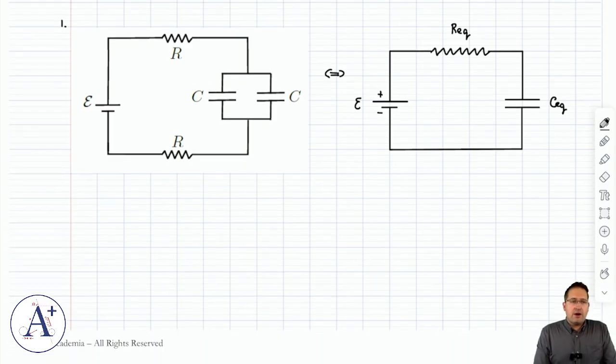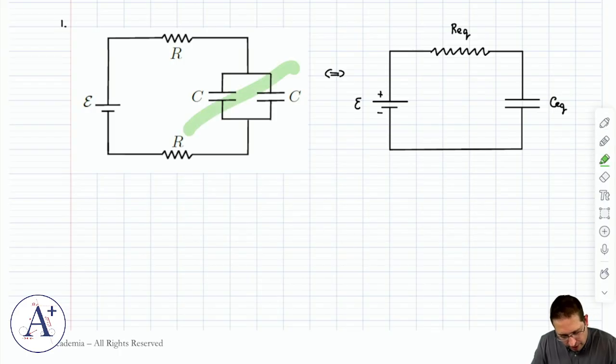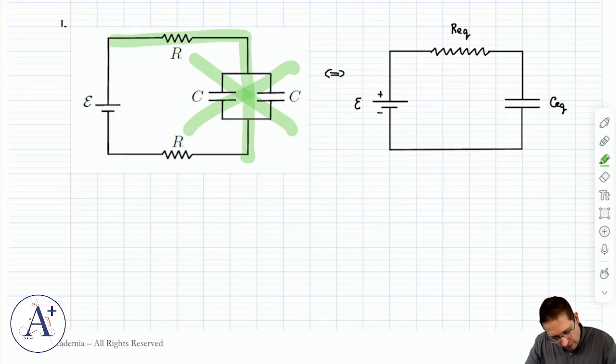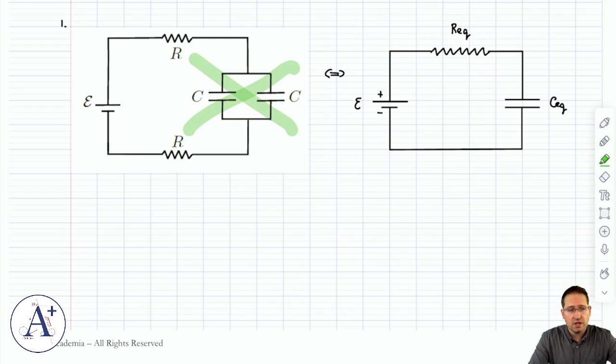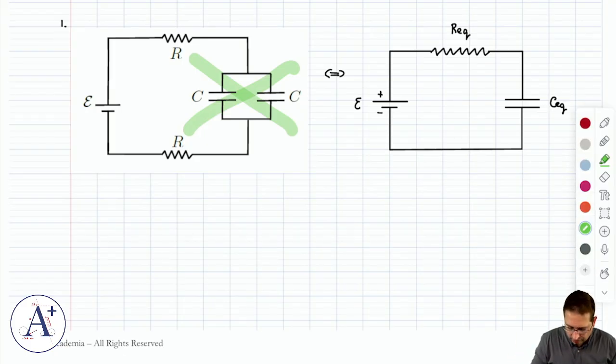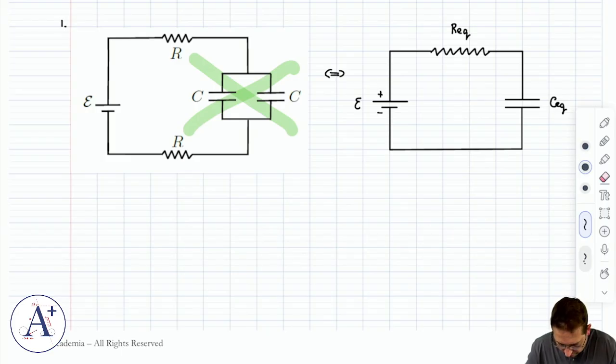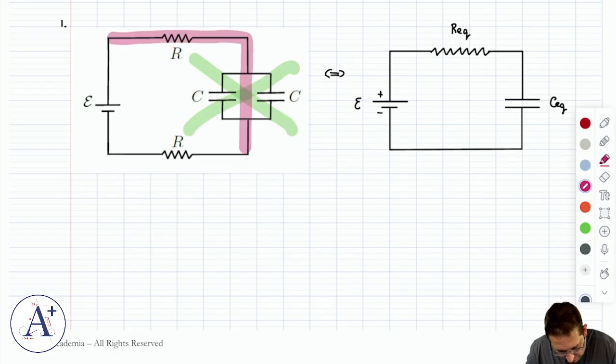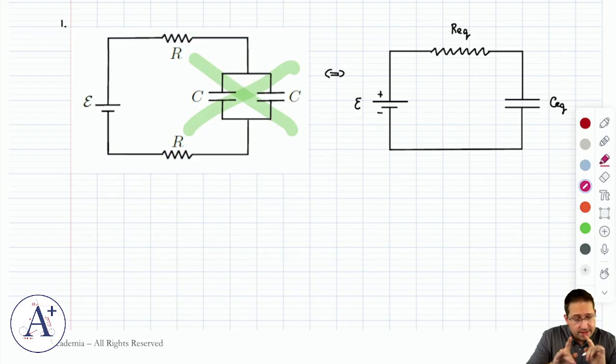Now, you might say, well, how do I deal with resistors in series and capacitors in series or parallel or whatever if I have a mix of them? Well, you separate them out. Let's forget about capacitors for a second. Just imagine they're not there. Are the two resistors, R1 and R2, in series or in parallel? Careful. In series is always easy to spot. They're one after the other. Any current that flows through this one must then flow through the second, which is the case here.